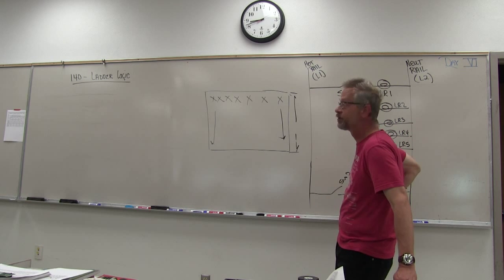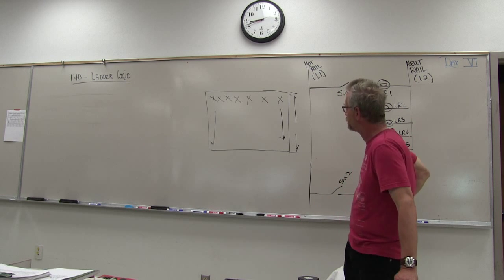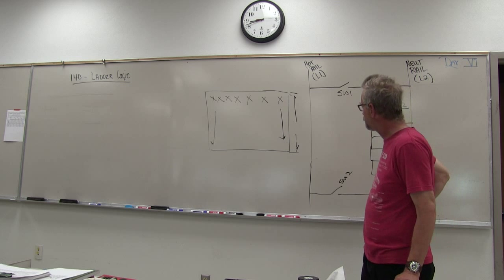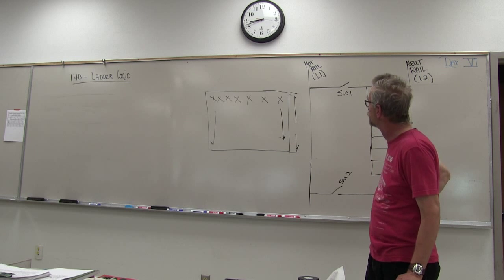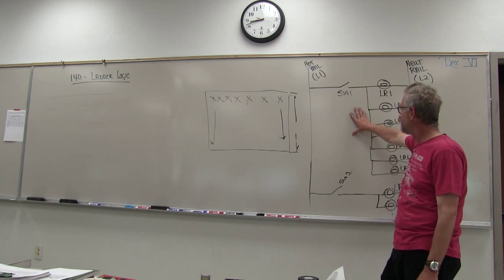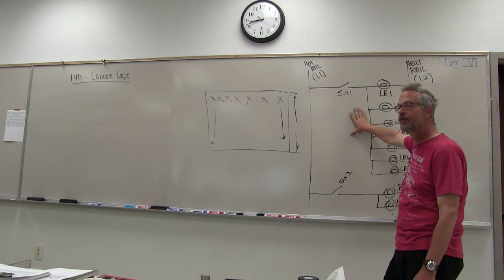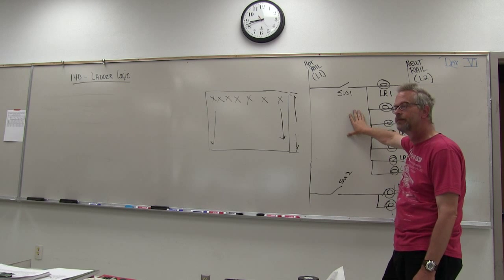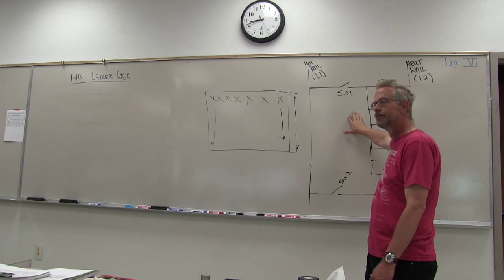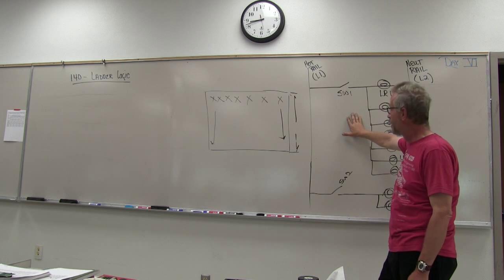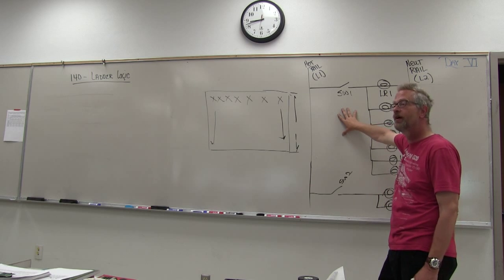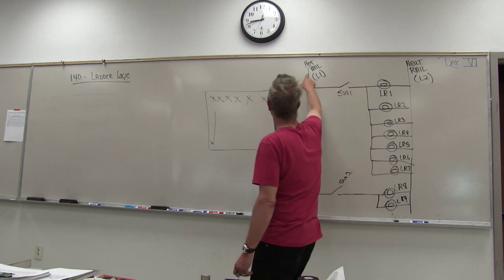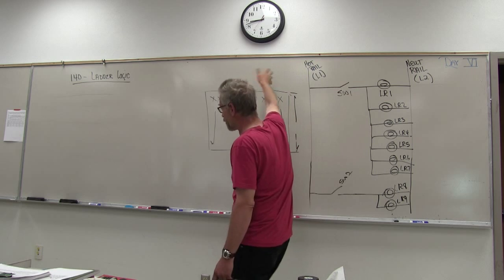The power comes into the same box, but they could be on separate circuits, because you can only run so many lights on one circuit. But that would be a different ladder logic diagram. If you just drew this out, you wouldn't know that there's only one circuit in that box right there. From the ladder logic diagram you would know that, because you'd have a bigger picture where there was more than one hot rail.